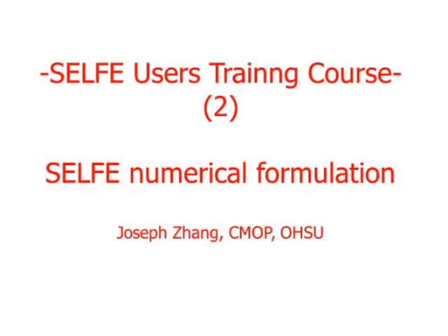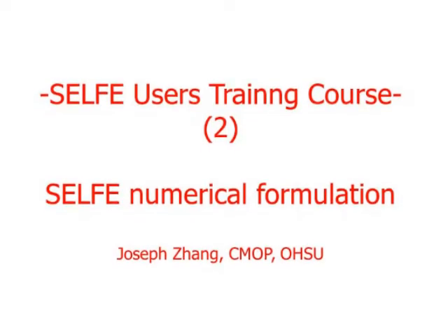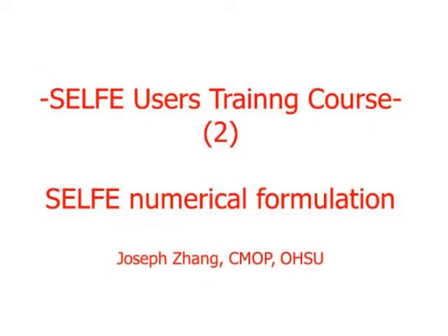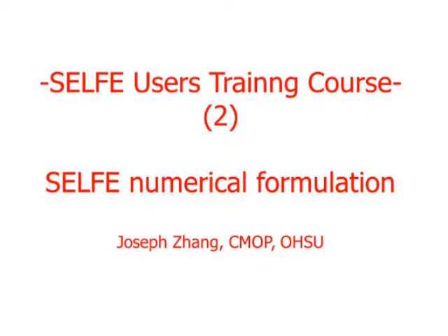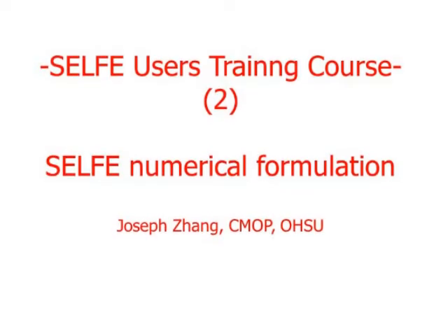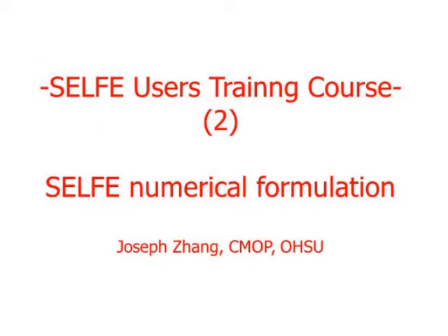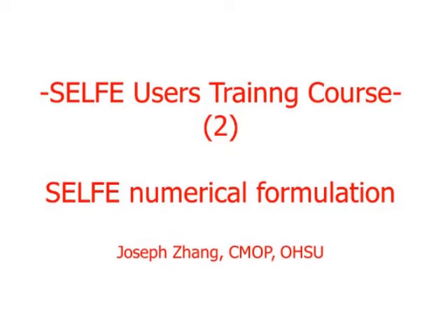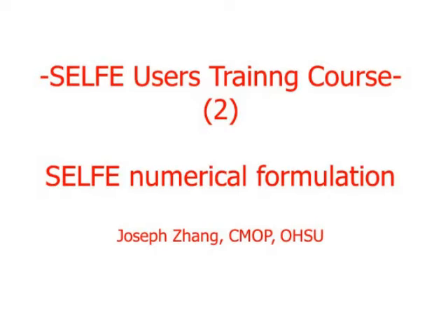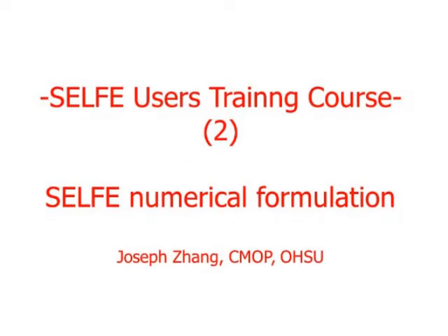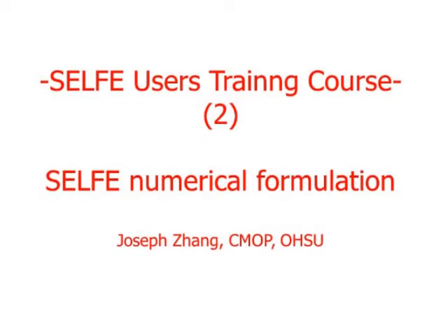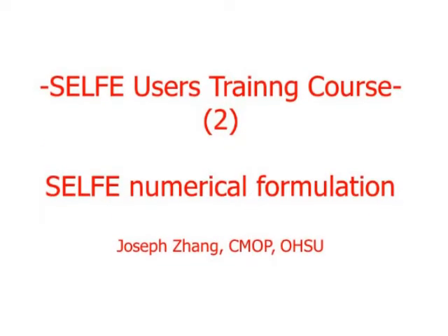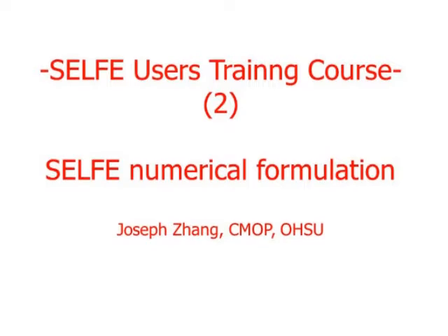That's really important for unstructured grids because you cannot assume anything about the distribution of nodes. Number two, if you look carefully at this algebraic equation system, the matrix consists of a bunch of geometric quantities that will never change unless you change the grid. So you can invert the Kriging matrix once and use it again and again during time stepping. So it's actually a very efficient method.